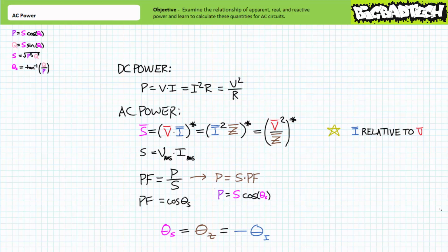This is the facts, and we are stuck with it. This being said, I kind of understand the inconvenience. Given inductors are assumed to be complex impedances defined as having positive vertical imaginary components, and capacitors are assumed to be complex impedances defined as having negative vertical imaginary components, you should ultimately get an apparent power angle, either positive or negative, that favors the impedance nature of the element in question.